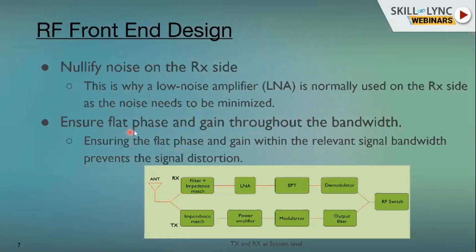So that's why you need to have flat phase and gain. It has to be linear behavior. So that is one of the challenges while designing both transmitter and receiver within a specific area at less cost.